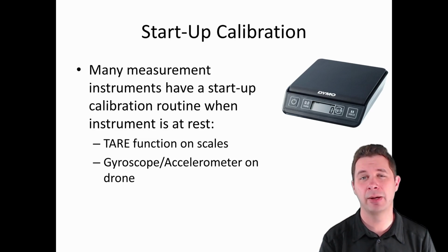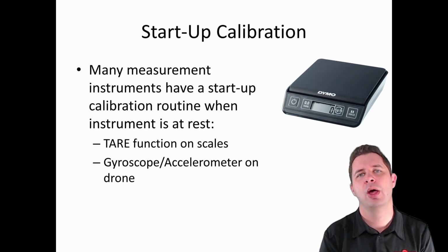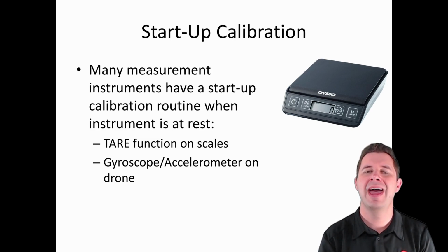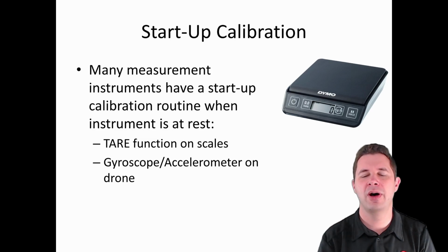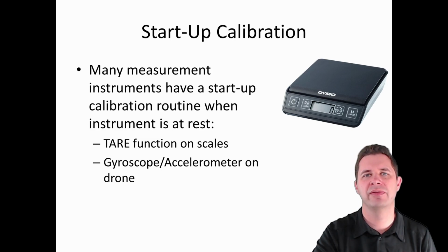Another place this startup calibration is used is with gyroscopes and accelerometers for little drones and things like that. You basically need to put it on a level surface to begin with and leave it for 5 seconds, and it learns what its level position is. It calibrates that sensor for a level position, and then when you use it, it knows where it started off as a level position, and that will be fine for maybe 10, 15, 20 minutes, whatever it may be, depending on the quality of the sensors.